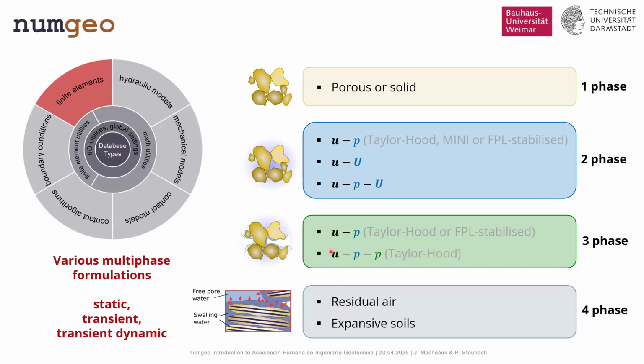All these formulations you can use in static or quasi-static simulations, in transient cases, but also in transient dynamic cases, for example, for earthquake loading. And this holds true not only for the saturated case, but also for the partially saturated formulation.